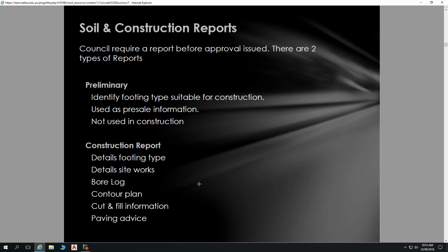What's important to engineers also is not just the footing, but what's happening around that. What's happening with moisture? How are we getting rid of moisture? What we don't want is water pooling in places. If we've got collapsible soil, we don't want water right next to the building, lubricating sands so that they sit close together. If we've got reactive soil, we don't want moisture sitting next to the building to make the clay swell in winter and then shrink in summer when all that moisture has evaporated. What we want to do is get moisture away from the building.